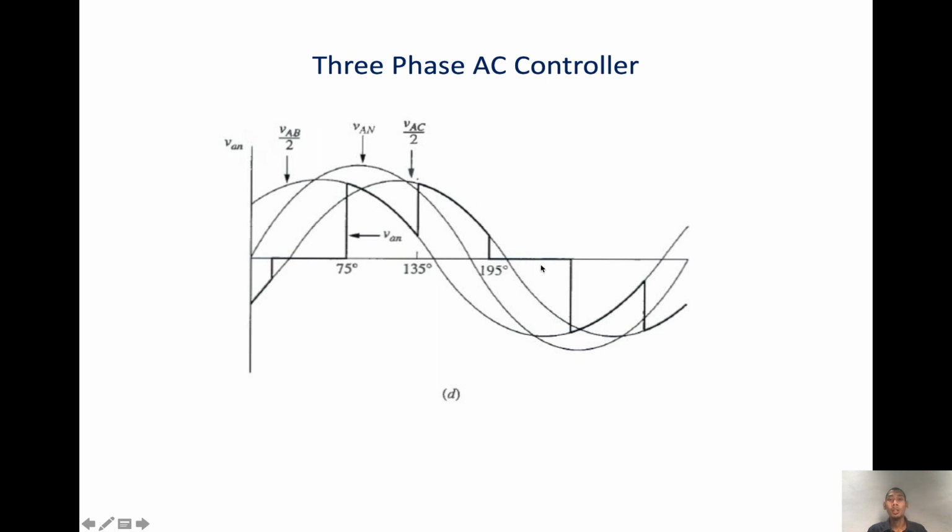Okay, and then this is no thyristor on, and the negative part repeats the same. So whenever you want to plot the chart, you must know the sequence of the thyristors and how many thyristors are on at that particular interval of time. So this allows you to plot the output voltage instantly.